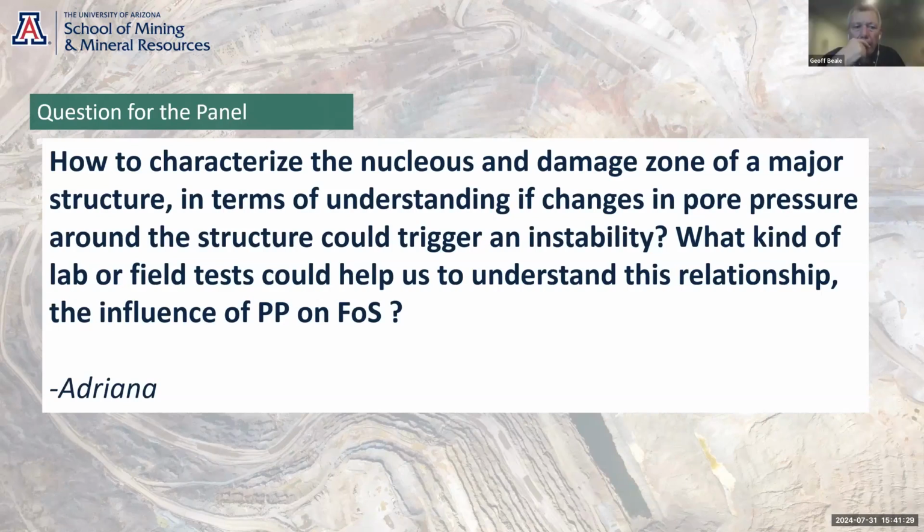Yeah, and the question there says lab or field tests. Well, lab tests on a fault are difficult or not very satisfying at best. I mean, faults always differ along strike and dip. So you do a lab sample at one place and it's going to be different a few meters away probably. And the same with field tests, to try and measure a permeability on a fault and apply that to the whole fault is probably misleading. But the piezometers will actually tell you how the fault responds, and therefore they will tell you whether water's getting in or whether it isn't getting in.